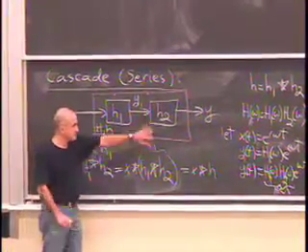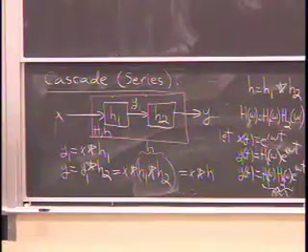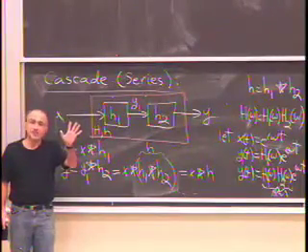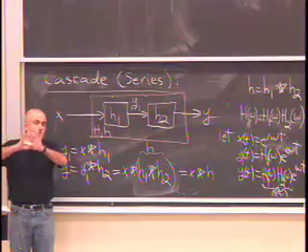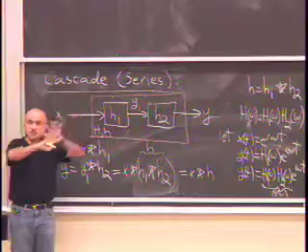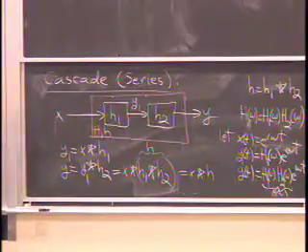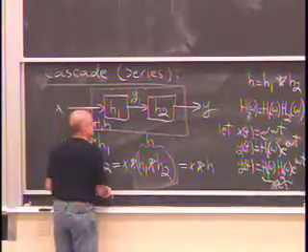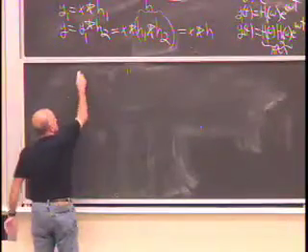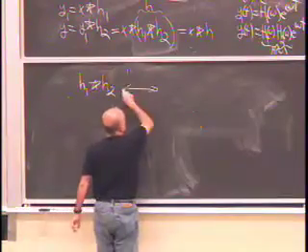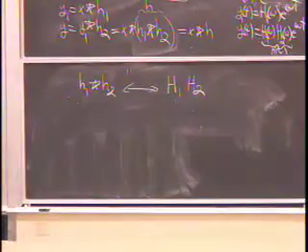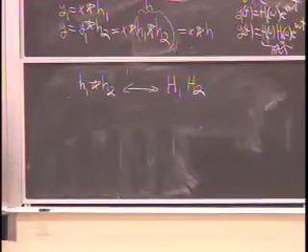And so it's important to keep this in mind for discrete time systems. I've walked you through that problem in the problem set. But essentially, the upshot of that problem is you get a polynomial of order n, a polynomial of order m, you multiply them. You get a polynomial of order n plus m, and the coefficients of that new polynomial are obtained by convolving the individual coefficients of the two polynomials that you multiply. And you get it by this relationship, that convolution in time is multiplication in frequency. That's one of the golden rules of this course. Convolution in time is multiplication in frequency.